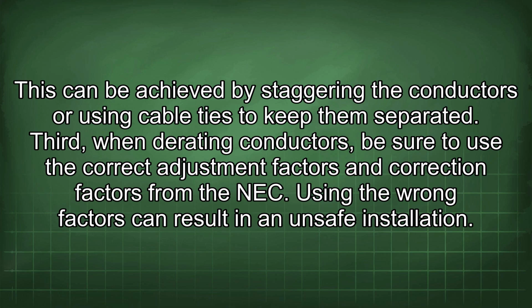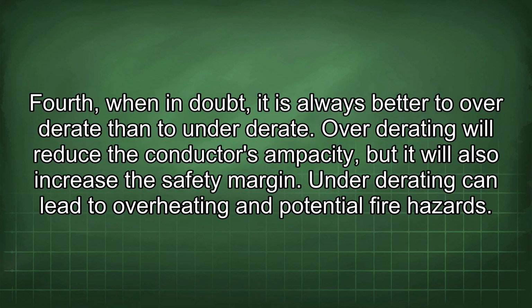Third, when derating conductors, be sure to use the correct adjustment factors and correction factors from the NEC. Using the wrong factors can result in an unsafe installation. Fourth, when in doubt, it is always better to over-derate than to under-derate. Over-derating will reduce the conductor's ampacity, but it will also increase the safety margin. Under-derating can lead to overheating and potential fire hazards.